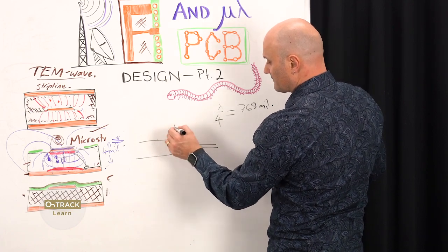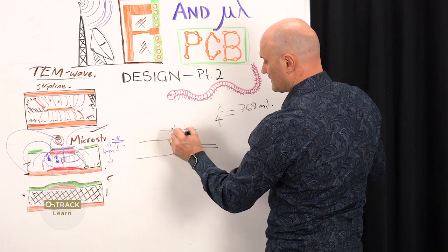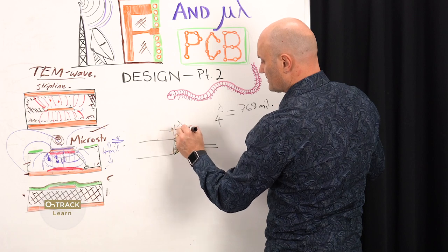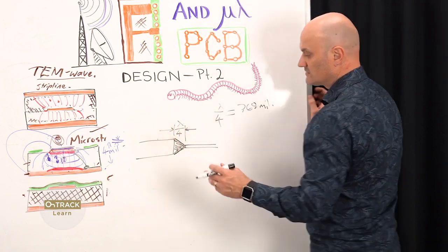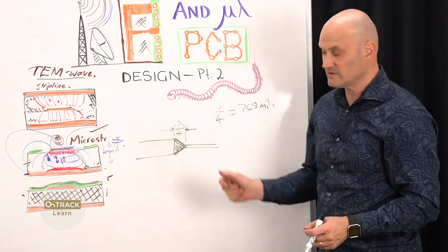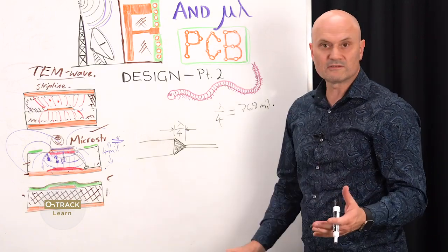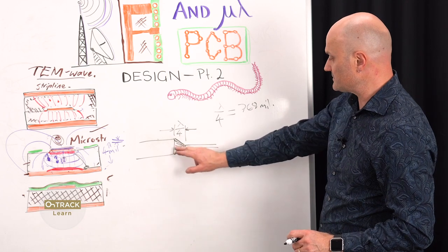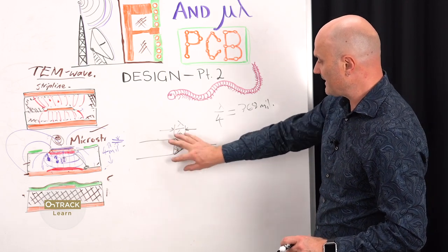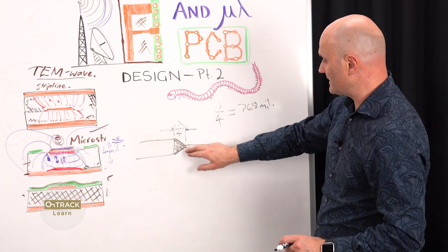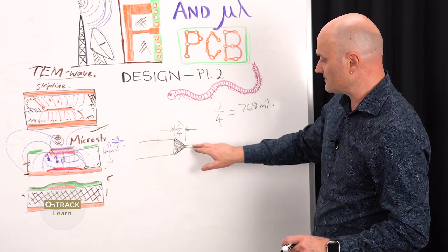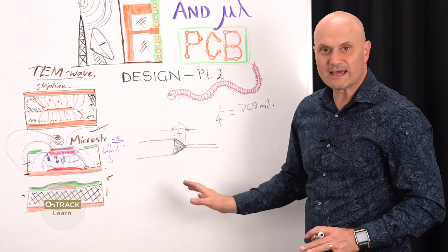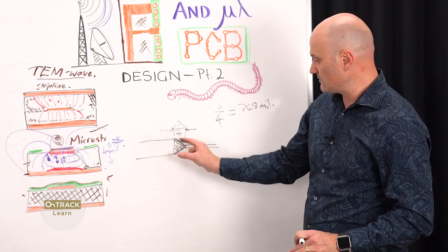And that length of that tapered segment is 1/4 wavelength long. Maybe you don't have room for that, and can you tolerate the reflections if it's got to be shorter? Well, as a circuit designer, you have to know that. But generally what we do is we insert this tapered section, and that gives a gradual transition from one impedance to another, and pretty much eliminates any reflections if you do it that way.